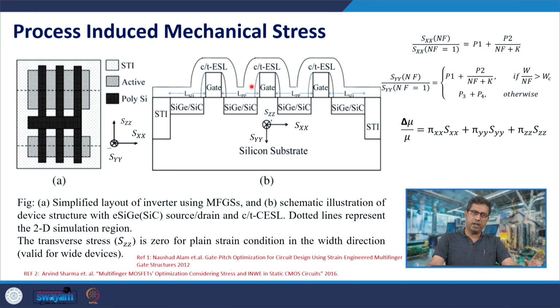So with different kinds of stresses, the mobilities of the electrons or holes increase. Accordingly, the stresses are applied. So this mechanical stress is applied. For example, using a stress layer of this kind, one can apply a compressive stress or a tensile stress, depending